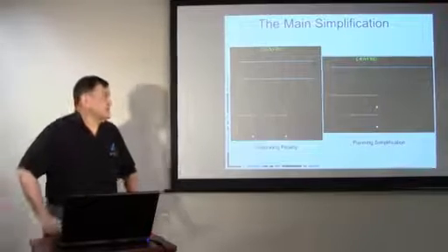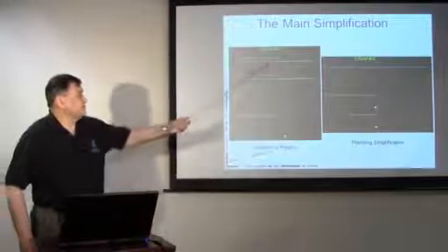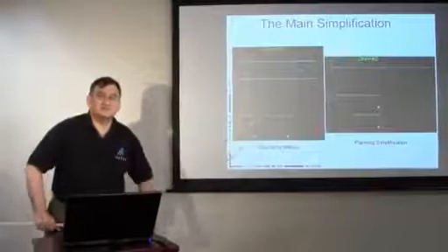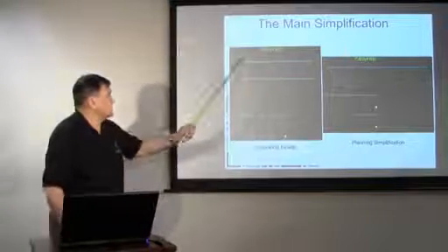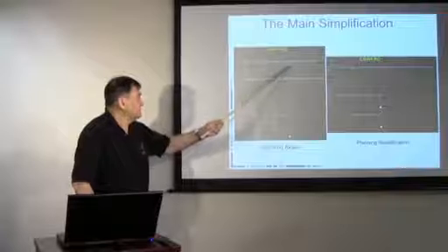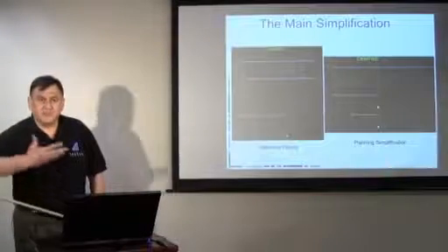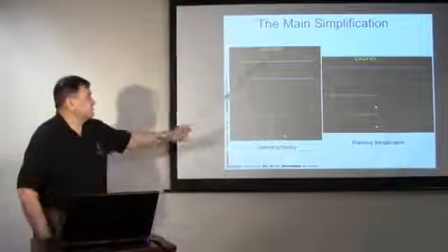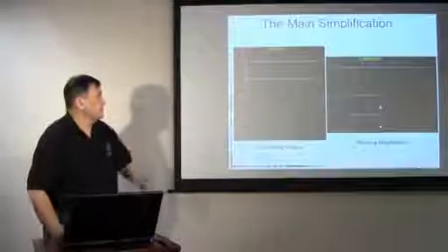Another main simplification is that planning models are bus-oriented. And what we mean by that, we can see it here with an example of the Crawford station taken out of the PALCO system. In the real world, we actually have a 230 kV breaker and a half configuration for the lines, and then a double breaker for the load. And remember, we said a breaker and a half is because we really have 3 breakers shared between two lines here.